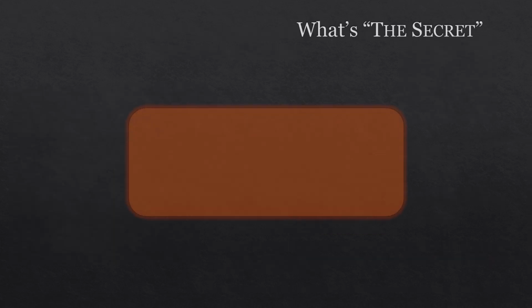The secret? There's got to be a secret. Well, the secret is based on science. Debris is attracted to moisture. We know this. Even a Swiffer that started out as a dry mop now is moistened. However, for the microsurfaces that are fiber optics, we can use too much solvent, or we can use the wrong solvent, or we can use the wrong tools. The science is in product selection and how the products are used.